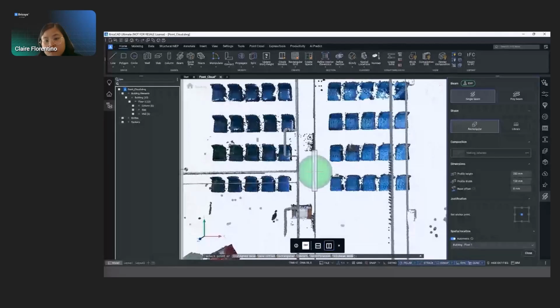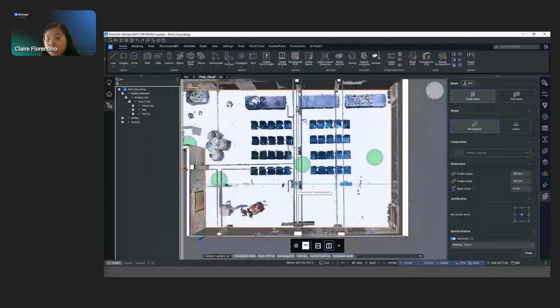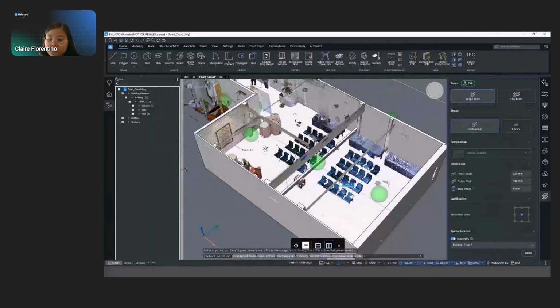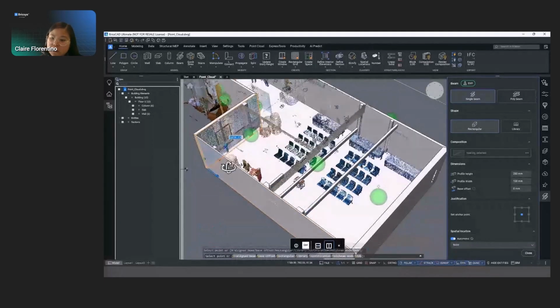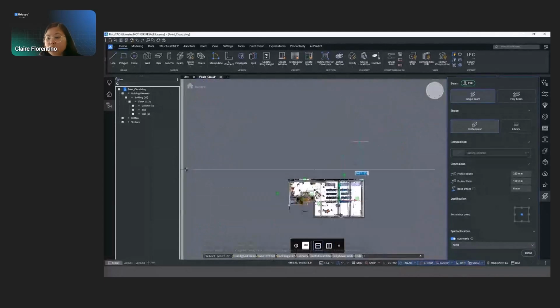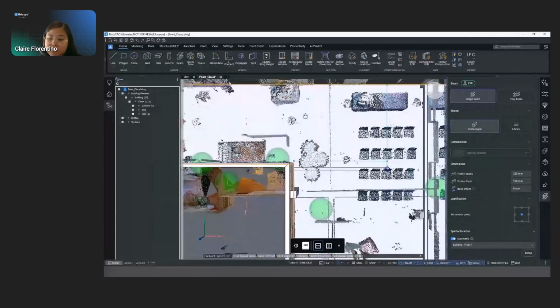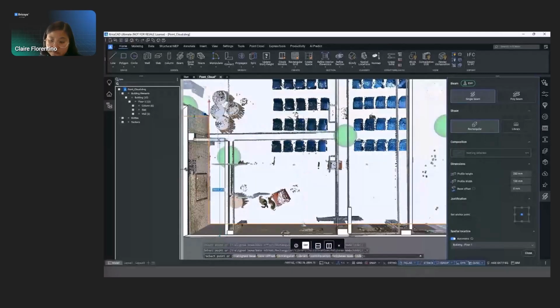So just like the columns and walls, the beams also have their own panel in BricsCAD. It also allows us to choose which type of beam to use, or if you just want a 3D solid and further detail that later, that's also fine. You can dictate the dimensions and just place the beam segments in a few places in your model.